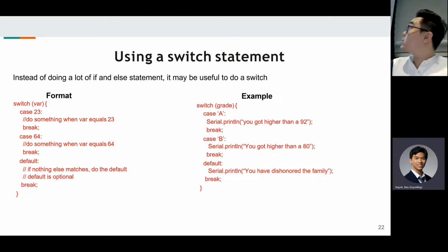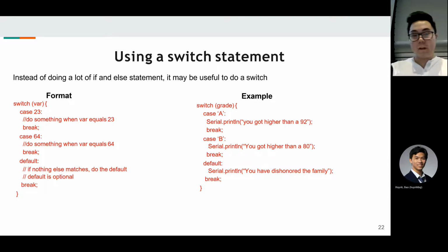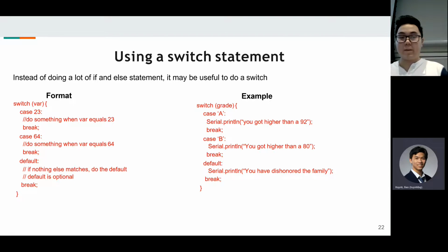And for those that are well-versed, there are switch statements in C++. I mean, Arduino C, which do the exact same thing as C++, and make sure you have a default case or you have problems. Yes. So is the syntax for Arduino essentially just C syntax with a couple of differences? Yeah, it pretty much is. I think the more interesting part is getting used to sensors. The sensors can sometimes be really janky because they come with their own libraries and different things. So most of the syntax is roughly the same as C++ though.